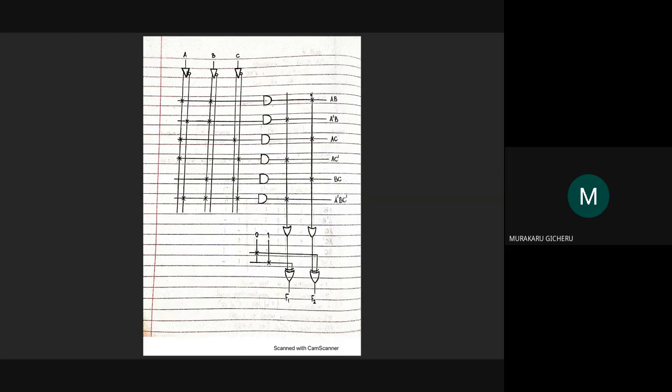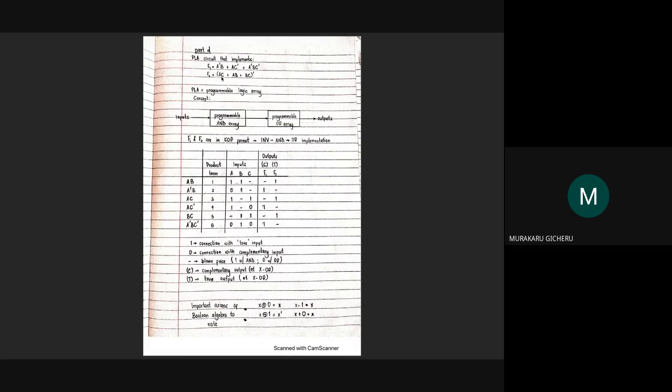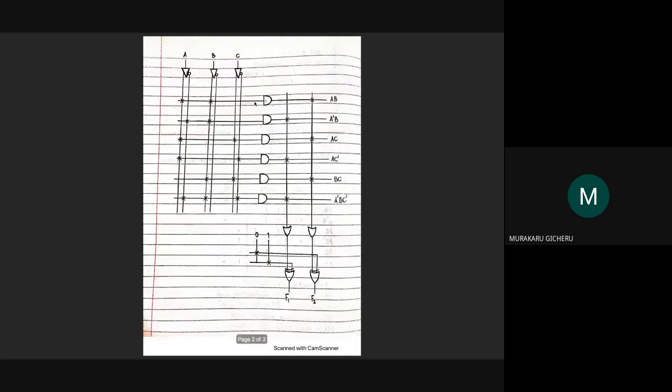And then the same thing here. According to this expression, we'll have AC or AB or BC. So here we have AB, we have AC, we have BC. Those will be kept intact, the others will be blown. And all of these will go into our OR gates down here. And this is the part where these axioms will apply, the ones for XOR.